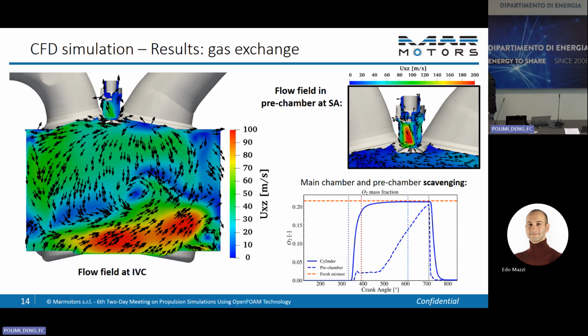All right, Andrea. Yes, my question is always on the pre-chamber. I don't know if you have looked at each point of the combustion diagram. Is the hypothesis of fully premixed valid, or are you more in the thin reaction zone flame regime?